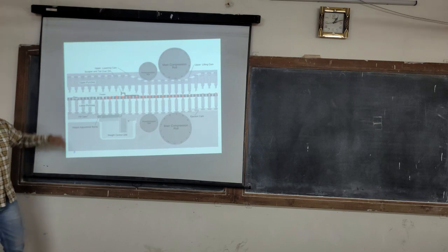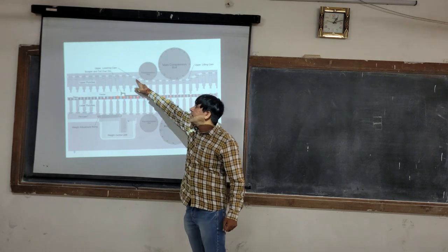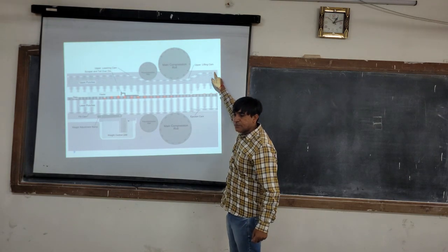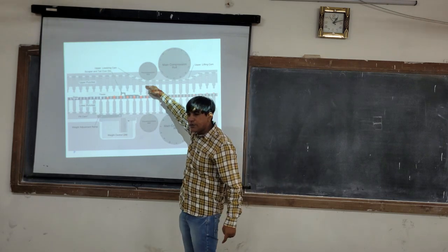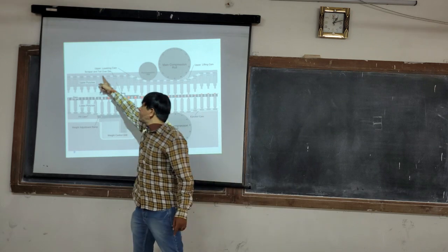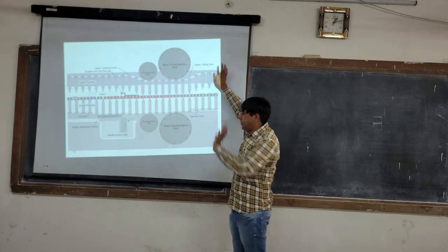These are the dies which are filled by material. This is a pre-compression roller. If you look at this, this is called the track. This will guide the upper punch. So the upper punches only enter the die cavity during compression. For the rest of the time, they are in a raised position.